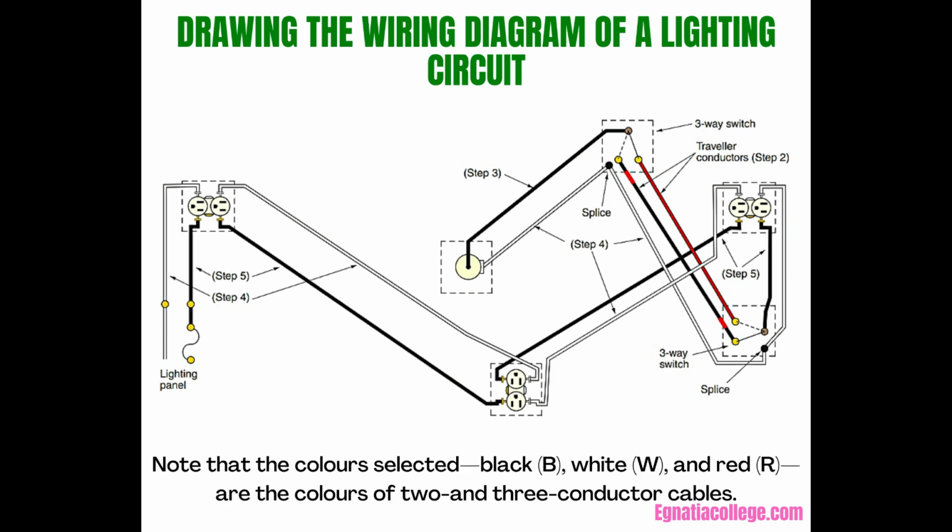5. Draw a line from the ungrounded, hot terminal on the panel to connect to each single pole switch and unswitched outlet. Connect to the common terminal of one 3-way switch only. 6. Show splices as small dots where the various wires are to be connected. In the wiring diagram, the terminal of a switch or outlet may be used for the junction point of wires. However, the CEC does not permit more than one wire to be connected to a terminal unless the terminal is a type approved for more than one conductor. The standard screw-type terminal is not approved for more than one wire.